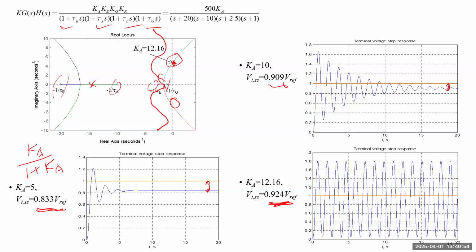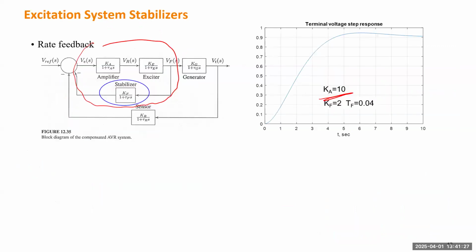Okay, I won't go into further details, but I suggest you play with this Simulink model and the model with the stabilizer provided by the textbook. You can play with those 2 files by setting different values. There's a possibility that if you properly select that new pole, you can make the root locus further from the imaginary axis. That will give you more stability margin, but you need to select a proper value. It doesn't mean any value for tau and k will give you better stability.